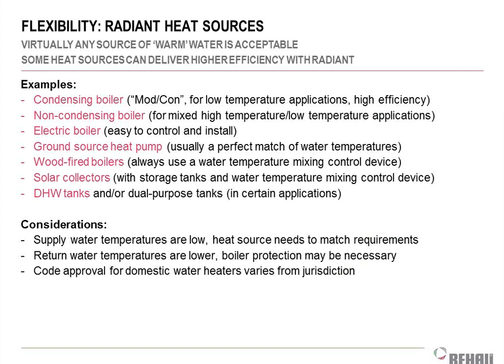And you could use a water heater. We are not fans of this at TEC. I know some guys do it. But you could use a regular water heater to feed your radiant floor. It seems kind of stupid to us that someone would spend all this money doing all this radiant stuff and then cheap out and not buy the right boiler at the end and get an inefficient water heater to do it. Right? Why would I want a 60% efficient water heater when I can have a 94% efficient boiler? Plus, if I use a water heater, I still have to add other safety devices onto the water heater for using it on a closed loop system anyway. So it doesn't really make a lot of sense, but technically you could do it.